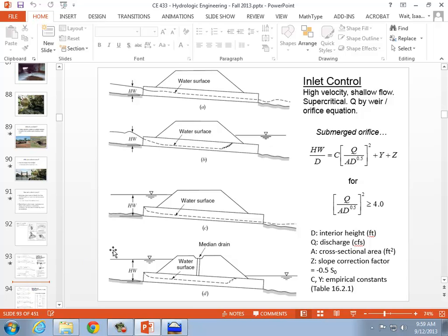So it's conceivable that there would be a case if the headwater was totally submerged and the pipe is only partially full, it may not have as much of an impact. I mean, so we saw that it went from 5.67 to 6.25. I don't know, that's maybe like a 15% improvement. It's not always going to be a 15% improvement under every condition. It probably varies depending on how deeply submerged the orifice is.